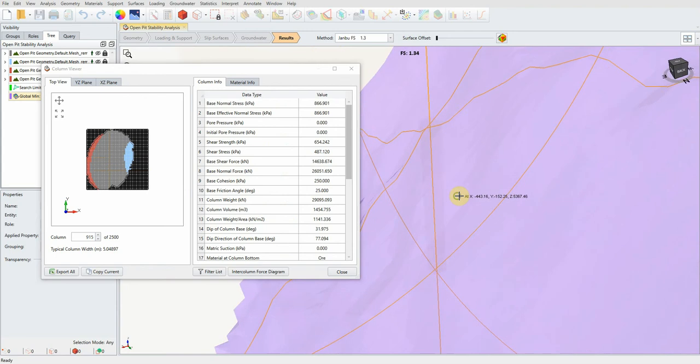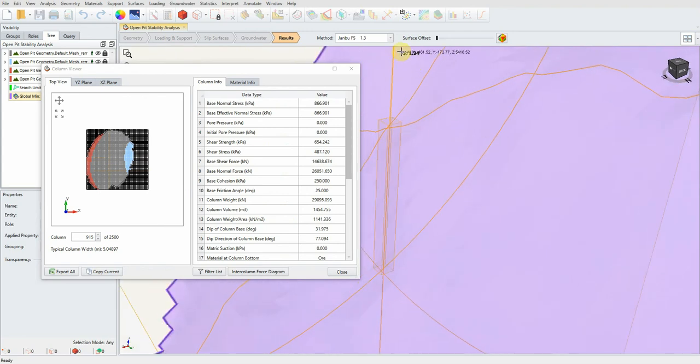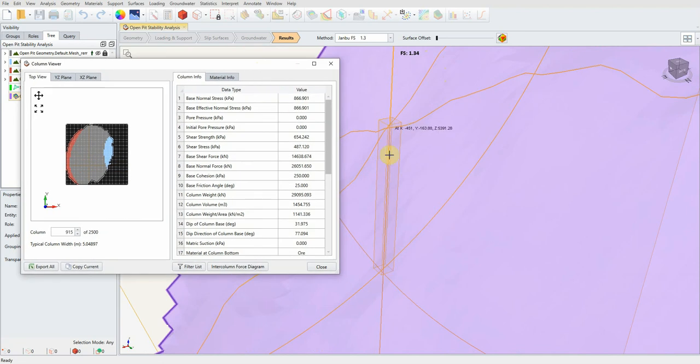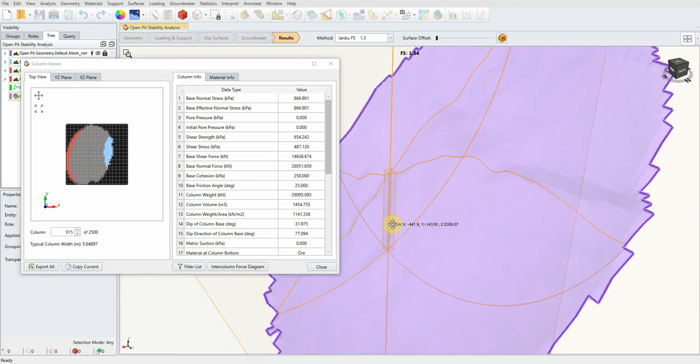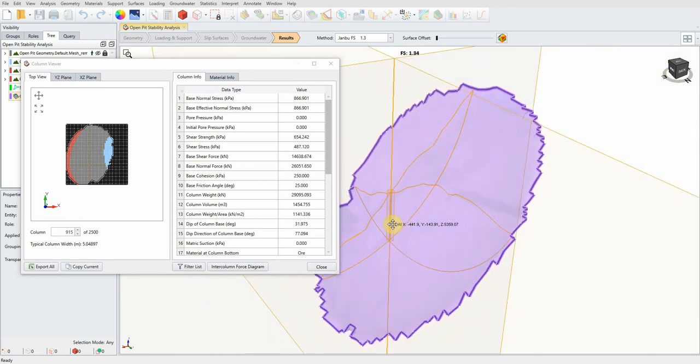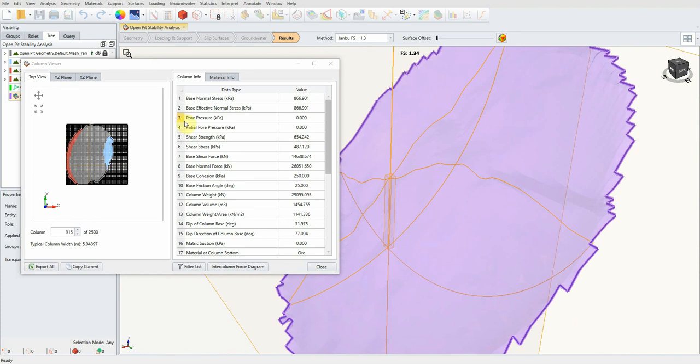And that explains why we have a higher factor of safety if we compare 3D to 2D slope stability analysis, because in the column we have 4 sides of resistance, while on the other hand, in Slide 2 we have only 2 sides of resistance, and that's why we have a higher factor of safety. Is this always the case? It always depends. It depends on the geometry and on many other factors. But this is just another great feature you can see in Slide 3.